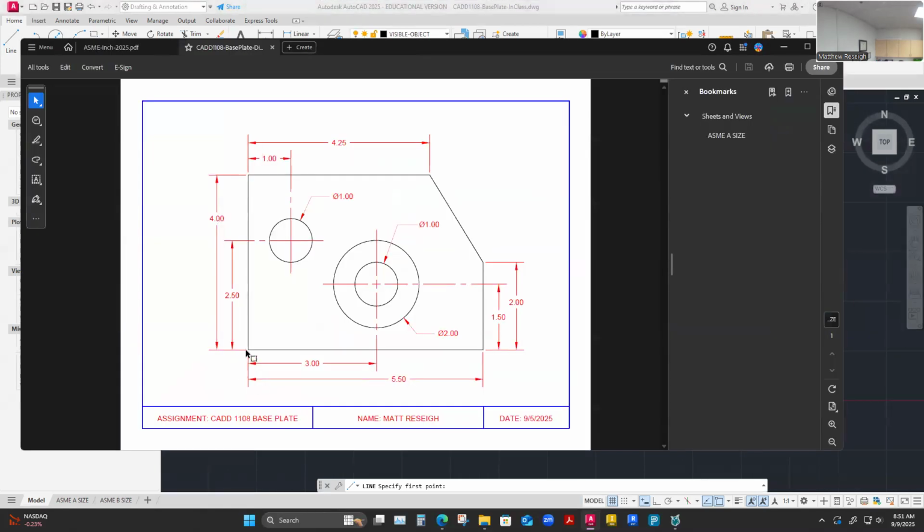This is a word I'll throw at you: a datum. I'm establishing this point on this object as having a lot of controls here. A lot of dimensions are going to come from this point. So in the future, sometimes where I'm dimensioning from specifies its importance a little bit. Obviously, I'm also pulling data from here, so I definitely have multiple datums, or places where I'm establishing where to pull dimensions from. Eventually, when we get into dimensioning, we'll talk about some of the rules of that.